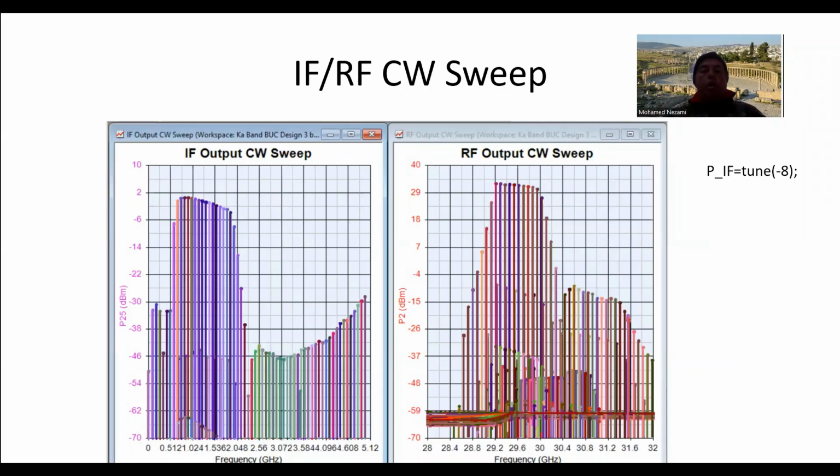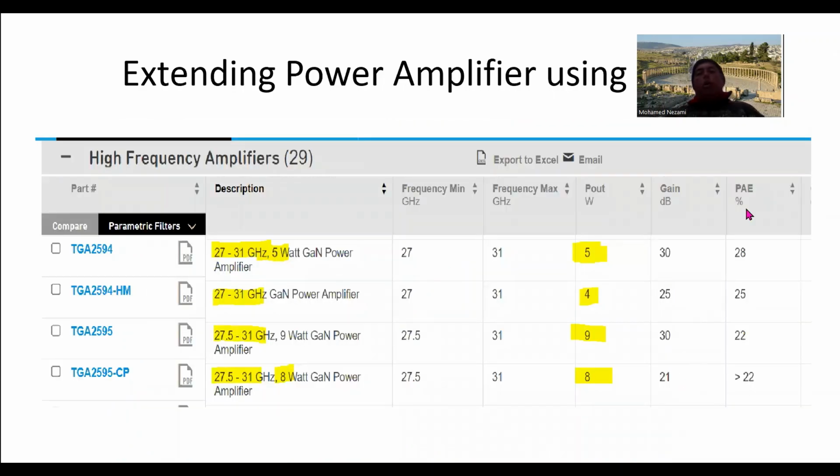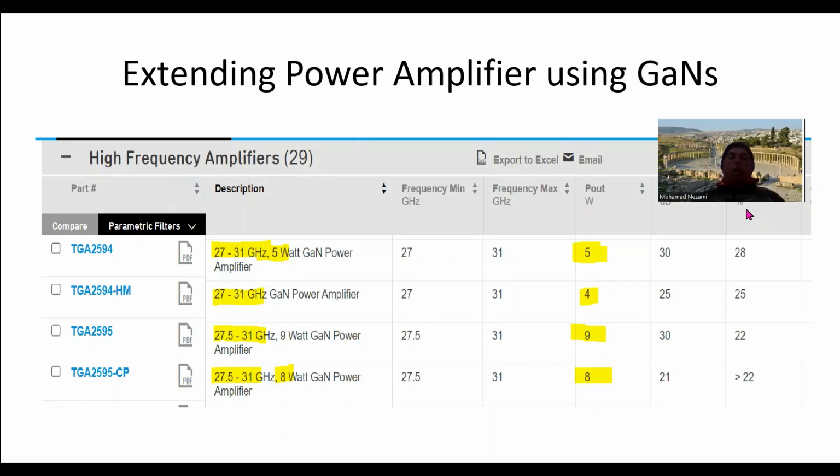The L-band modem is shown in here, and we could see all these components. Again, like I said, the slope will be dealt with on the actual PCB design once we start picking. So where do we go from here? What we have designed is really the intermediate power level section of the block up converter, the BUC. By the way, this design can easily be used also for 5G.